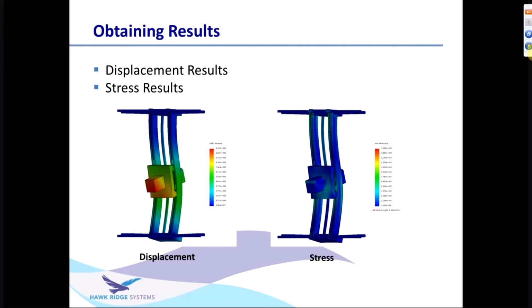And in this case, again, Ingersoll was really only concerned about the displacements and stresses. And going back, I'll show you in a minute back in SOLIDWORKS, but Ingersoll wanted the plots to be consistent with what they did for their fully bonded analysis, where they made essentially the maximum and minimum values in the plot legends the same across the X, Y, and Z displacement plots. And again, this just allowed them to compare the plots more easily.